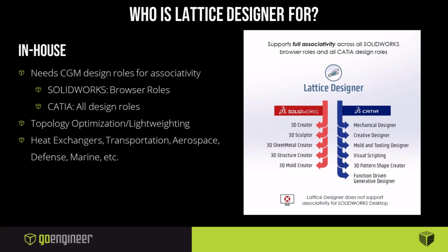There is a single caveat that I want to make. Even if you are using SOLIDWORKS Connected, even if you are using the Design with SOLIDWORKS connector for 3DEXPERIENCE, parts made in Desktop SOLIDWORKS will not maintain associativity with the platform. Desktop SOLIDWORKS parts can be imported into Lattice Designer, but they won't maintain associativity if you make a design update. That's not always a deal breaker for folks, but it is something that does need to be mentioned.